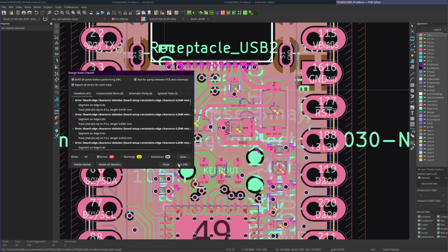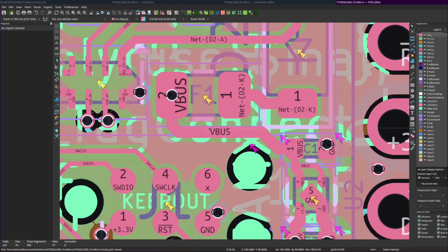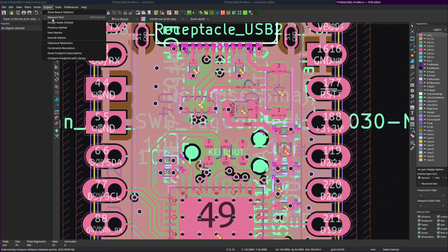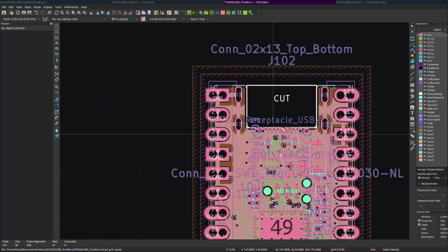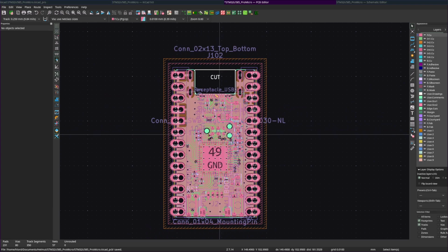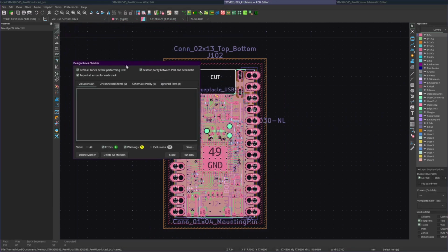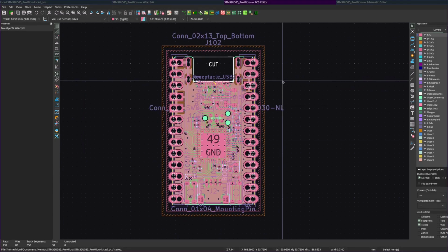In a future video, I hope to show you these boards working, maybe with this trace scraped up and tacked together, but working nonetheless. And now with those things changed, you can see that we have very few warnings remaining and no errors remaining in our DRC. Now let's get to setting up our job set to get repeatable outputs from this KiCad source.